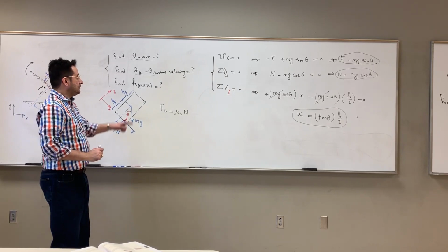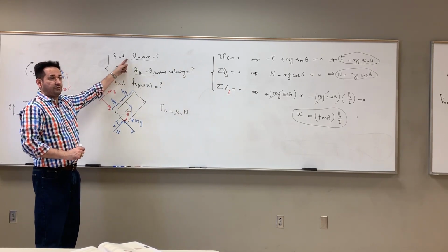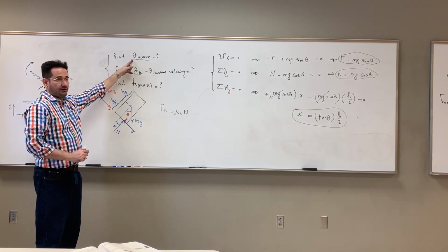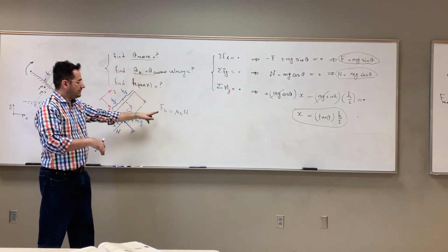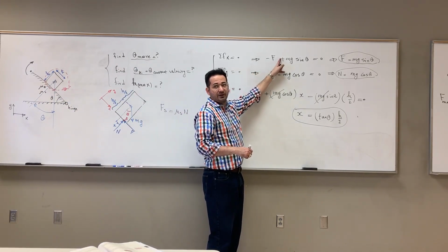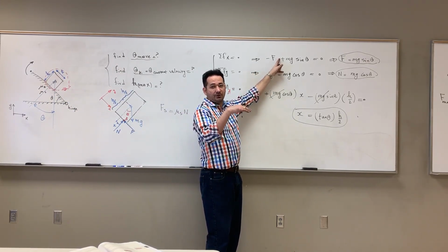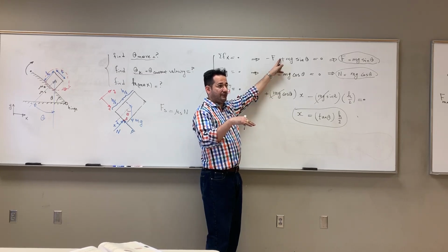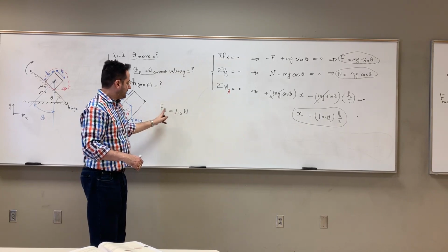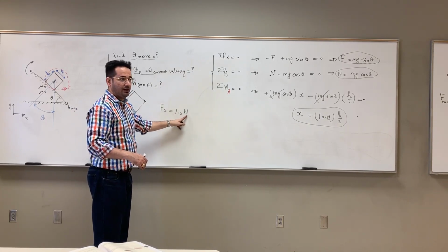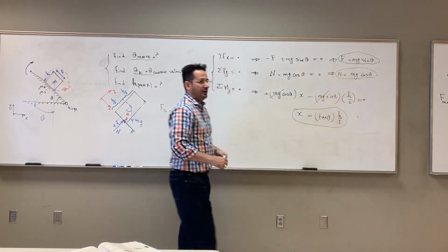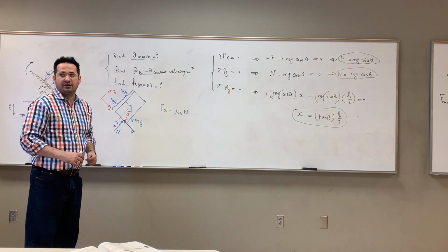But in order to answer this, I also need to apply the equation that is valid at this particular point. The maximum theta is the point that the friction force reaches. You see, this doesn't have a stop because it can be dynamic friction, static, everything. It reaches Fs, so at that point we have Fs equals mu s times N. Let's plug F and N into that equation in order to get theta move.